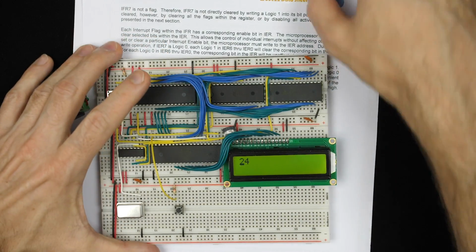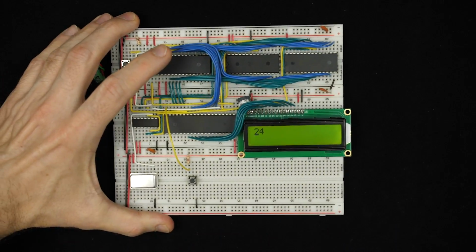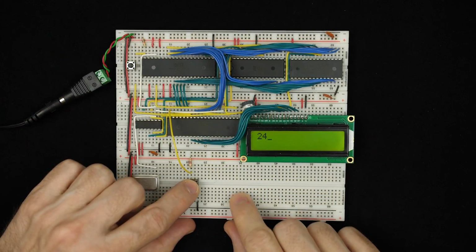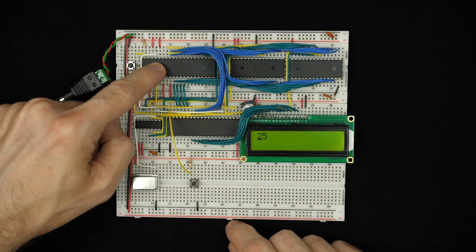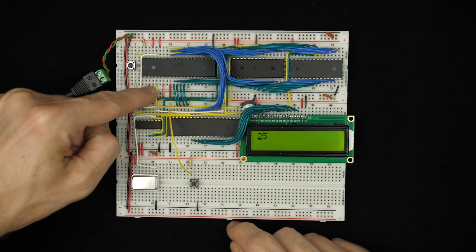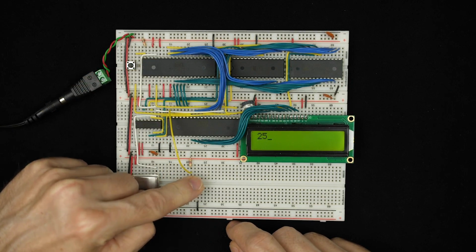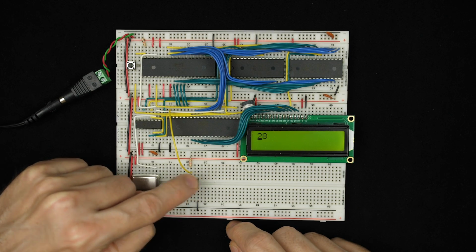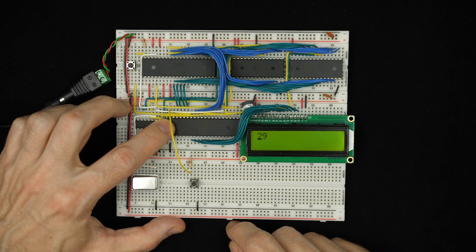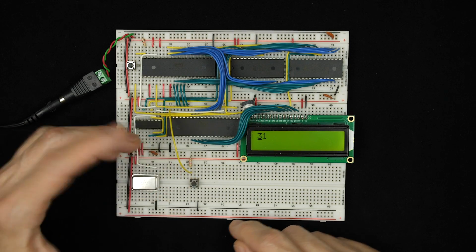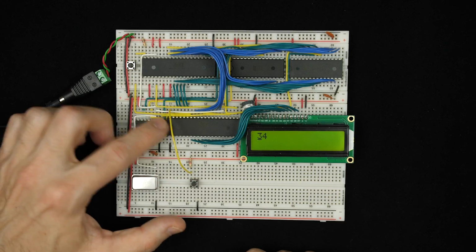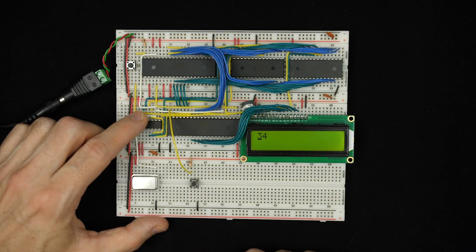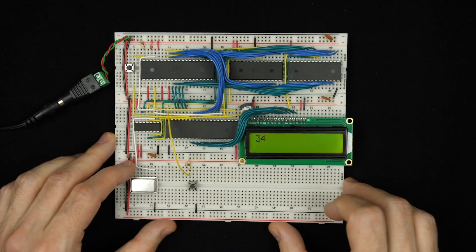But hopefully this gives you a sense of how the 6522 chip here can be used to have an interrupt coming in and forward that interrupt to the processor in a way that the processor can then service it when it gets a chance to run its interrupt service routine and then clear that interrupt. And also show a little bit about how we can use a delay loop to do a little bit of debouncing. But again, you might want to do that in hardware so it's not quite as laggy, or you might want to update the timer to be a little bit tighter. There's a bunch of things you could do to try to improve on this.